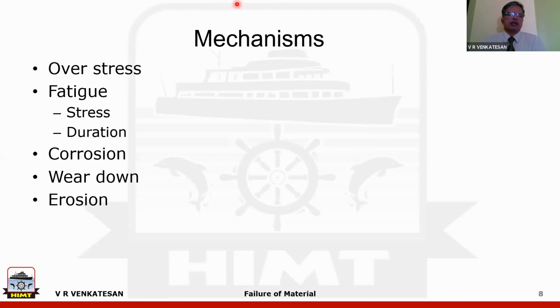So when you say there is a fracture, that is a mode, and that fracture can be because of these kinds of reasons. A part fractured because it got corroded and became less. It's a very common example, especially with hull structures. So the deck developed a crack. The deck developed a crack because, due to corrosion, it became very thin. So this is the mechanism, and crack or fracture is the mode.